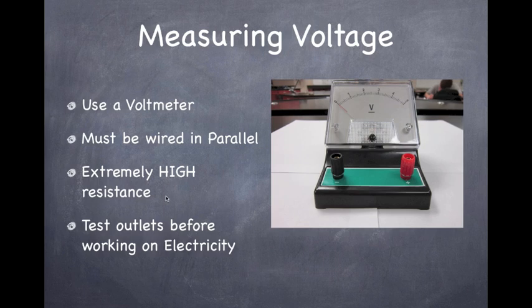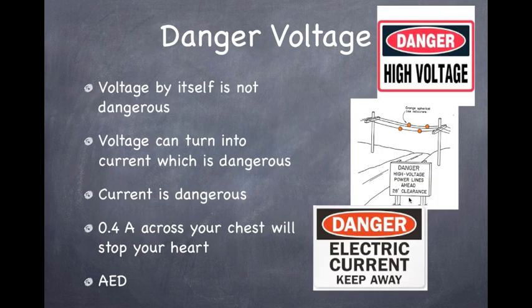Everybody should know how to operate a voltmeter. In fact, you should own one when you move out on your own. Whenever you're doing electrical work, it is very, very important that you test an electrical outlet before you actually begin work so that you don't get shocked. Other things that we can do to prevent shock is we can adhere to some specific safety rules.